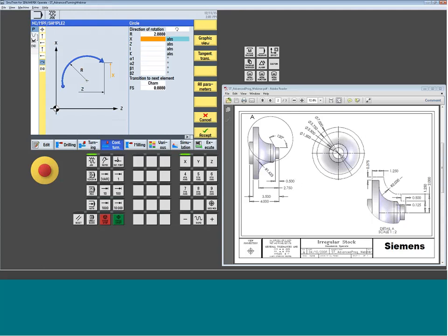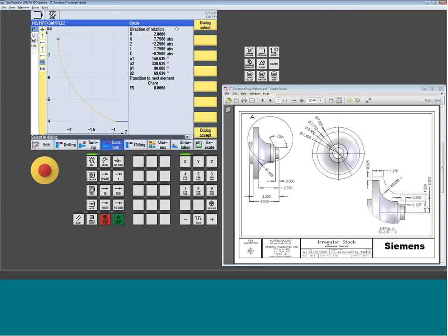So the end point is going to be out. Well, this diameter I know to be 7. And then we got another 3/8 per side. So I'm going to 7.750, right? If I know this back edge in this print is 3.5, left's 1.25, I would be going back to minus 2.25. Just do the math real quick. The center of my arc, let me give it, because I know it, assuming that it's even with the top point, and voila, I start to get an arc.